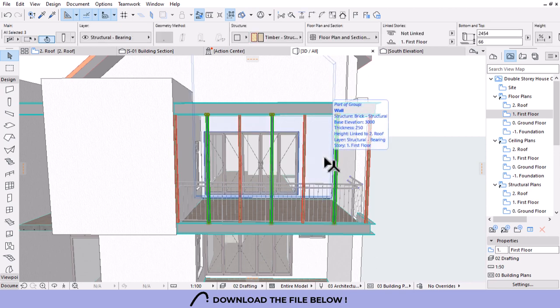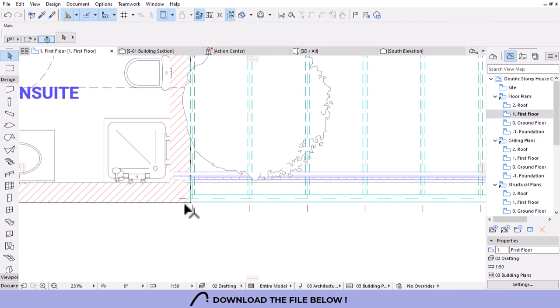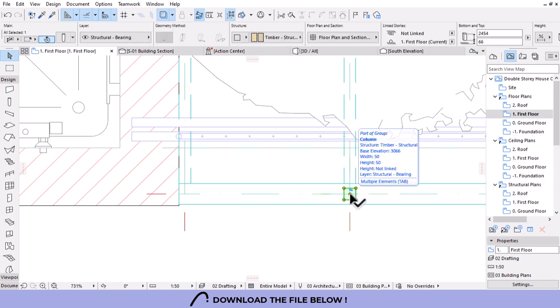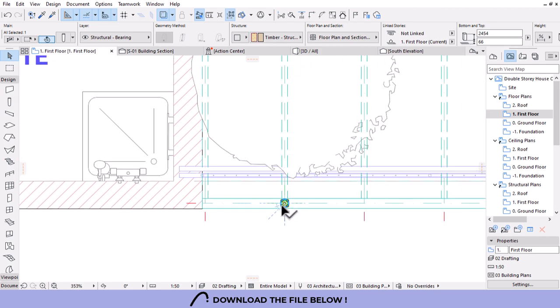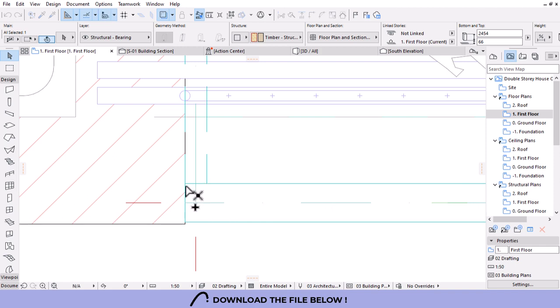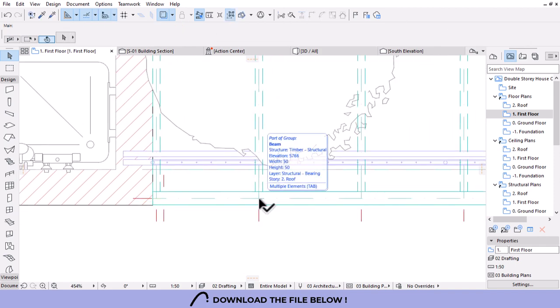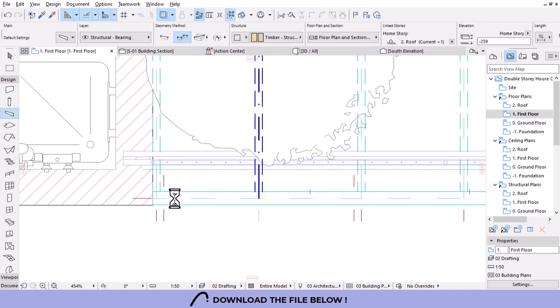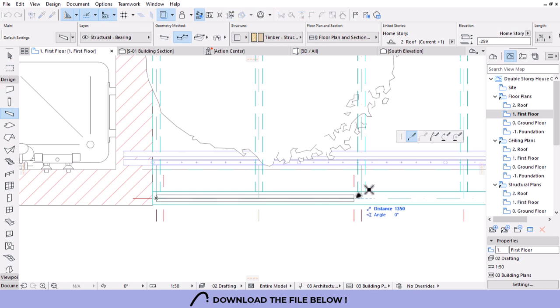You know what I want to do? I want to, okay, instead of selecting them that way, let's go to the first floor. What I would do, I'll hit on tab. Let's move this to there. I'll move a copy to this one, and then take the remaining one to there. And then I'm going to pick the parameters of that and draw a beam horizontally like that.